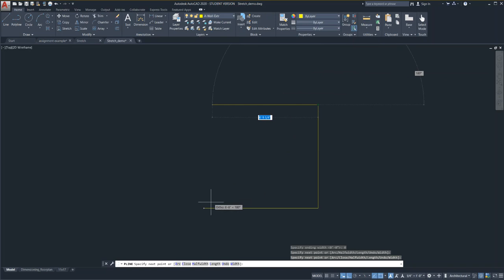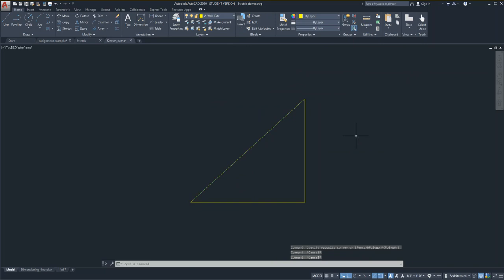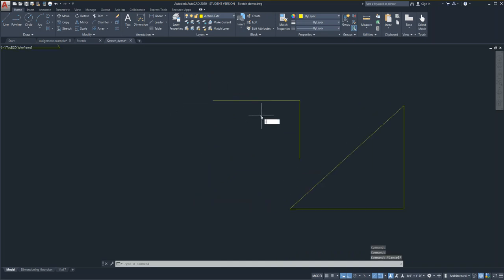Okay. So there's my polyline. I've created 3 segments and it's all one piece. But what happens when PL polyline, I create one length, enter again to initiate that same command, and I create a second length, and they're separate pieces, right? This is a polyline, this is a polyline, but they're separate pieces. Or I create lines, L-I-N-E, enter, right? And I click, click, click, and I have a line here, and I have a line here, okay?